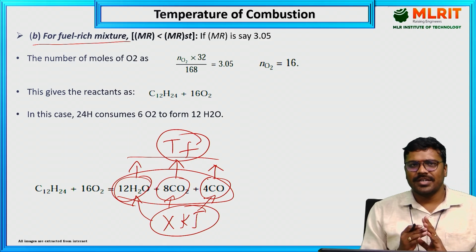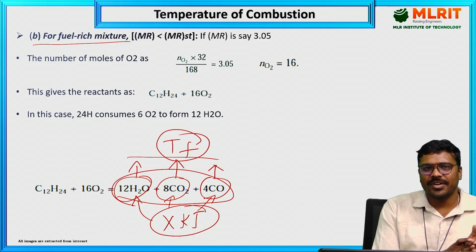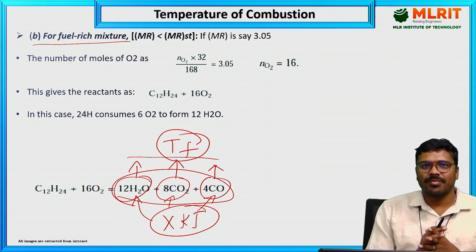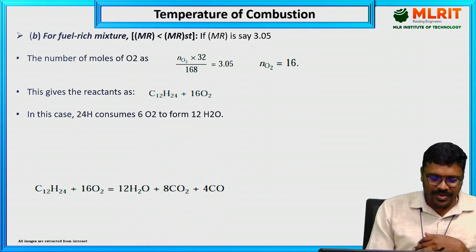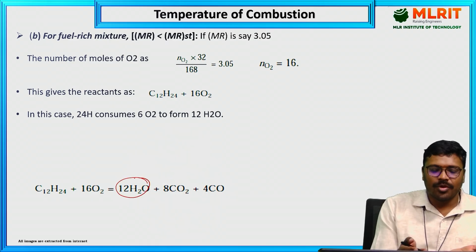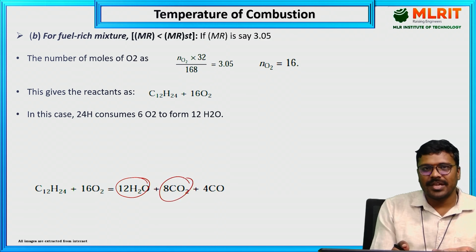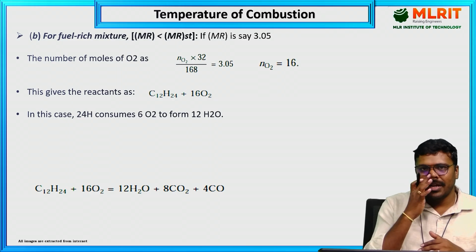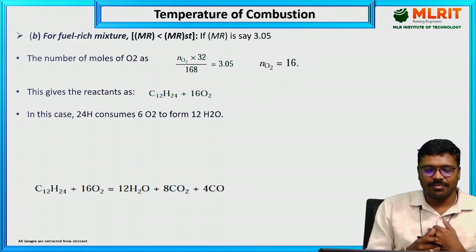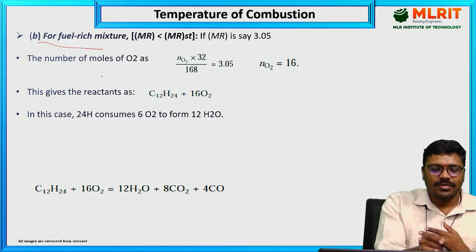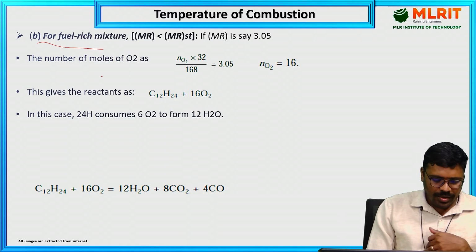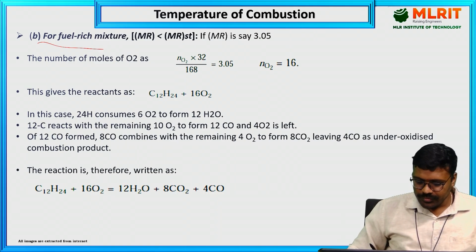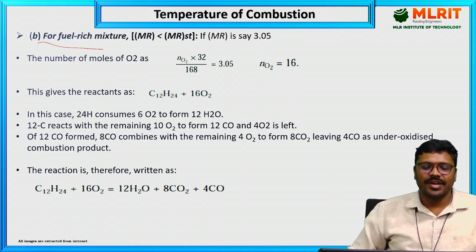Each one's heat absorption capacity will be different, because H2O specific heat will be different, CO2 specific heat will be different, CO specific heat will be different. So H2O may take more energy, CO2 may take less energy, based upon the specific heats. The final temperature will change depending upon the mixture ratio. So this is about the reaction for fuel rich mixture ratio.